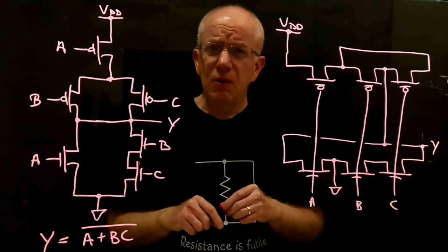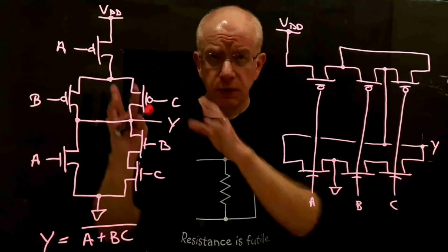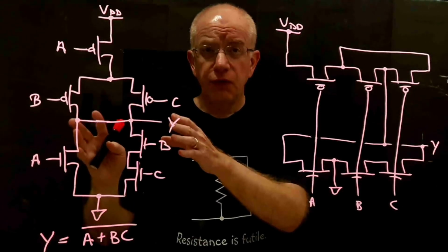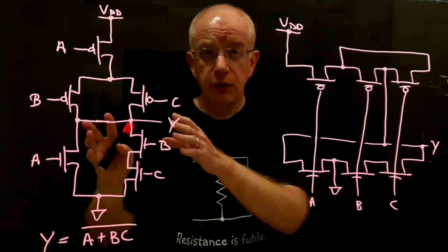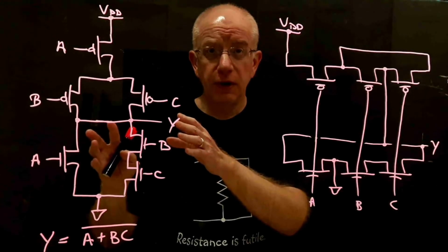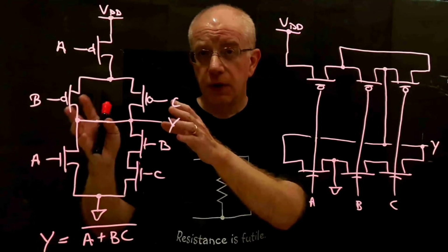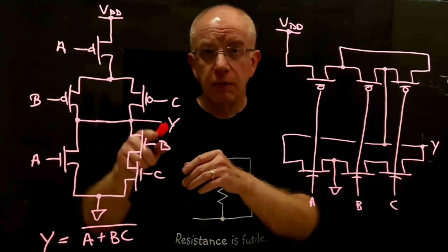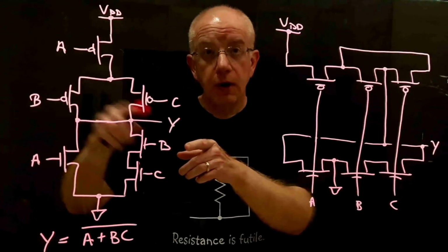And that's not really a great idea, because the way that you lay things out in the schematic view has to do more with making things intelligible to humans who are looking at your documentation, not how they might be better represented physically. In a schematic, we might connect things through just net labels, so there doesn't have to be physical proximity to make the wires short.